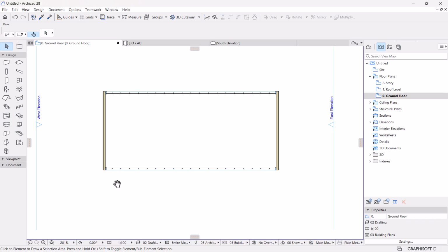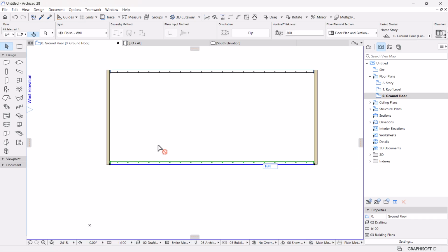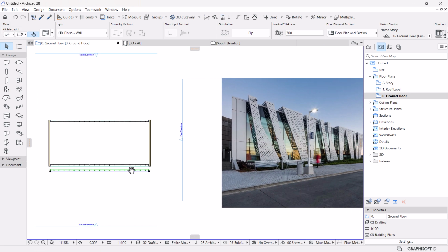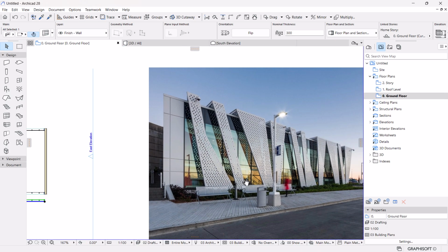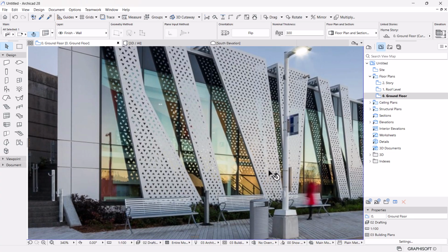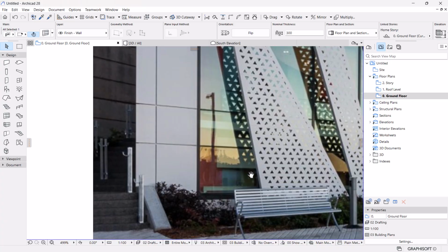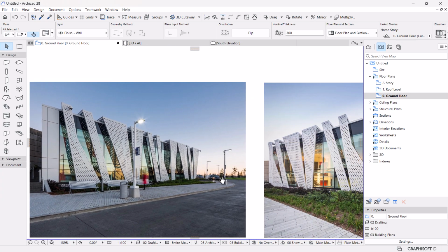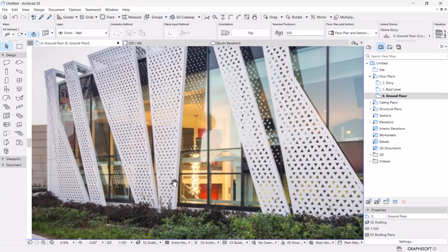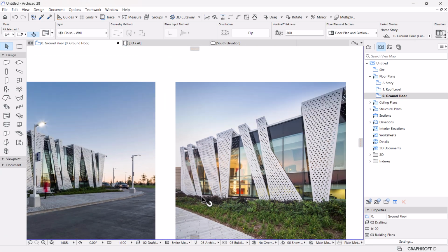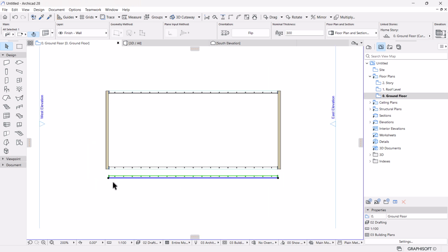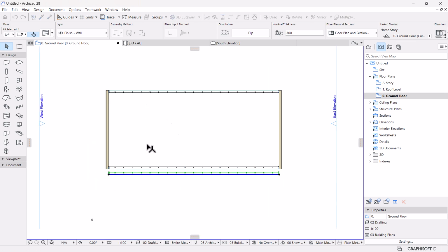elements. So to achieve this, I'm going to copy. Let's Control Shift D and copy this curtain wall, and then move it outside by 1 meter, because if you look at this, there should be a space between. There's quite a significant space between the glazing and then the feature. I don't know if it's for a person to pass, but it looks small, it looks tiny. I think we can analyze it better from this image. Okay, not that too much though, maybe around 600. I'm gonna move this back by 400.